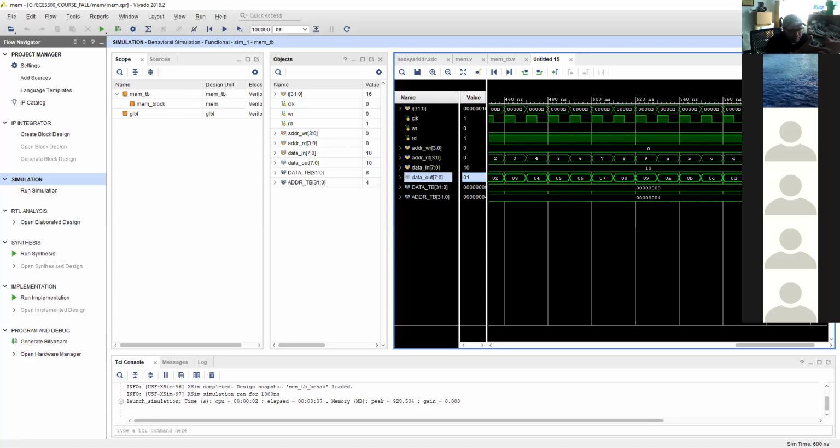We covered the accessory for the BCD with a trick asking you to display both the BCD and accessory by switching using a multiplexer. And then we started talking about how you can use the 2D dimensions register data type in Verilog for building a memory with different types of configuration. And we picked one of them, which has 2 pointers, one for reading and one for writing, with enabling the situation while you're reading and writing. And of course, this type of memory can read and write at the same time. And we wrote the code in front of you.